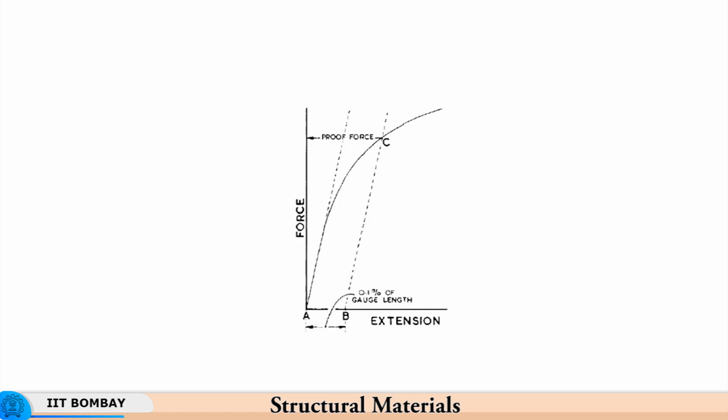So what is just undergoing plastic deformation? You have to define a strain. So 0.1% plastic strain, or 0.2% plastic strain, is defined as the strain at which you would say that the material has just about undergone yielding. The typical standard value of strain at which you take the stress, the so-called proof stress, is 0.2%, and so 0.2% proof stress is taken as the yield point, which is marked over here.